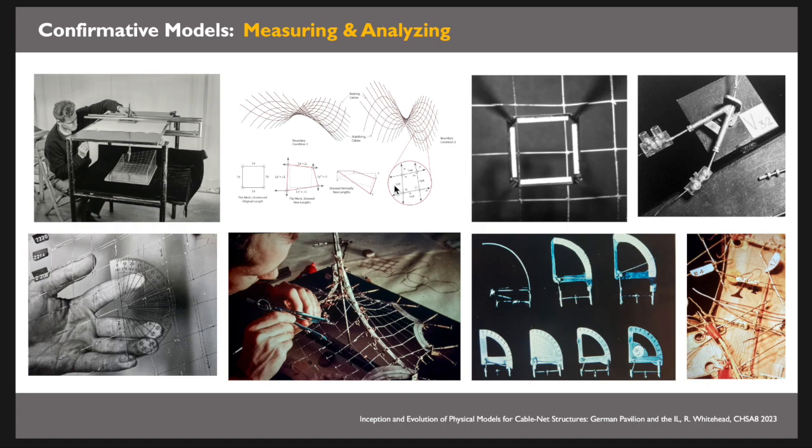Just as a quick example, a cable net, when you turn it into an anticlastic form, anticlastic meaning 1, 2 curves, so a double curvature. There's lots of different degrees of curvature you could get, right, between this one and that one. I want you to look at the difference between how a cable net that starts off as a square might then change from before and after, okay?